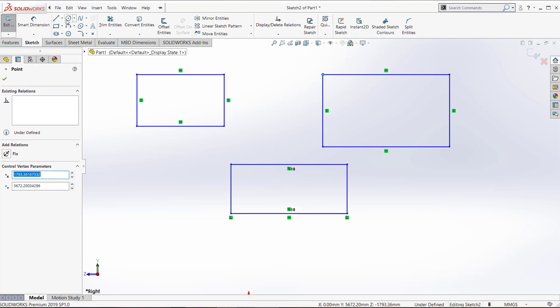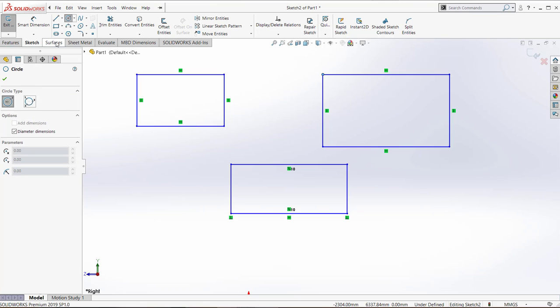And then we have the circle and ellipse and arc. These are 3 basic things that are round. So there are 2 types of circles. One begins at the center, and one is the perimeter circle. And as you can see, it starts with 3 points, or any arbitrary point on the circle, and then we have to click on the other 2 points on the circle.